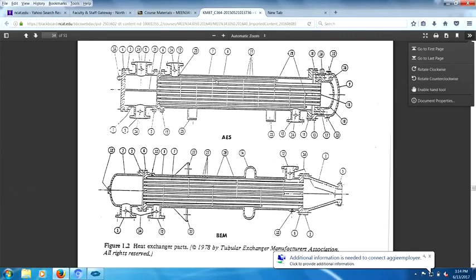I mean, I can weld. You don't want to buy my stuff, I guarantee you. These guys, you know, they lay down a really fine bead. Hopefully they'll lay down a fine bead. The first thing you want to do is see about their welding capabilities, their certification, and how they store their tubes. Now, if the tubes are up on a rack, that's pretty cool. However, if the tubes are laying down in a pool of water on a concrete floor and there's about 30,000 of them, you probably want to turn around and walk out.